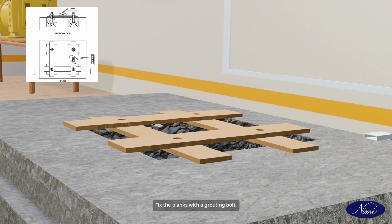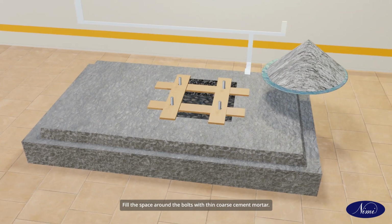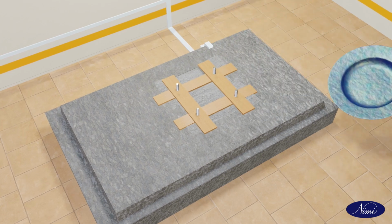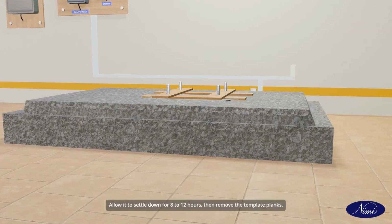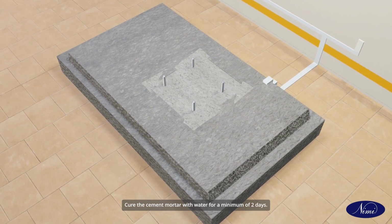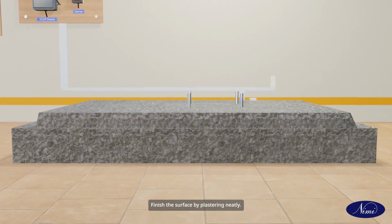Fix the planks with a grouting bolt. Check for level using the spirit level. Fill the space around the bolts with thin coarse cement mortar. Allow it to settle down for 8 to 12 hours, then remove the template planks. Cure the cement mortar with water for a minimum of 2 days. Finish the surface by plastering neatly.